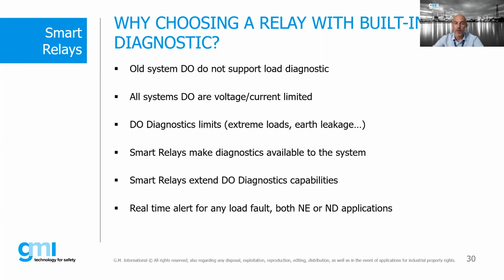Smart relay with diagnostic can make the diagnostic available to the system, and can report to the system the failure inside the relay or the load. The smart relay extends your diagnostic capabilities. Also the relay with built-in diagnostic can report any kind of fault, both for normally energized or normally de-energized applications. So for the moment we have finished.